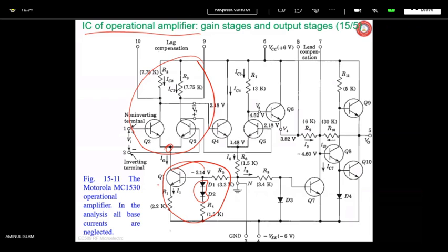It is not able to make any change in the current. No change means zero. For DC analysis, if IO equals constant, then for AC analysis we can think of it as if it is disconnected. It is almost floating. It is not getting any ground or something like that. For small signal or AC analysis, the constant current source is removed, that is, it is disconnected.